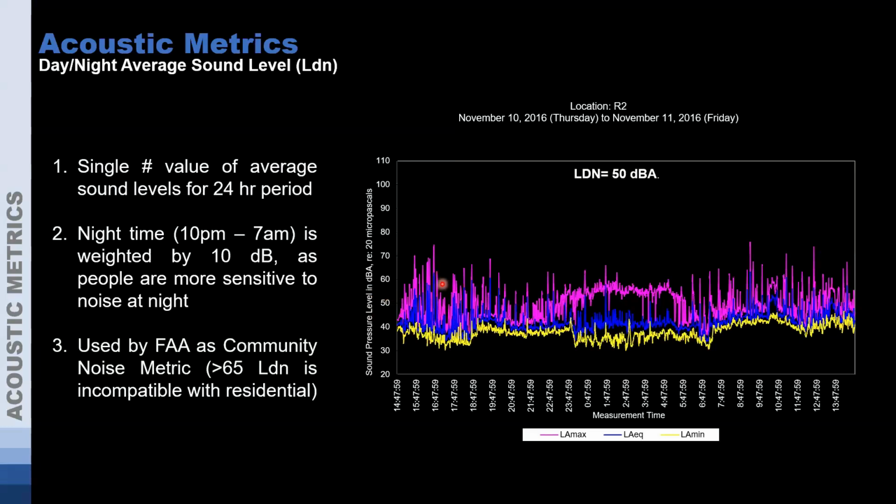So all of these, some of these 20 decibels are heard as 4 times louder even than that. So if you have these individual events, these individual overflights, those can still be disturbing even if you design around that LDN. You're just designing around an average, not the specific things that may occur there.